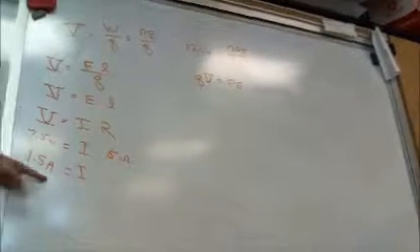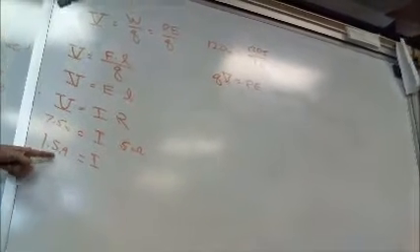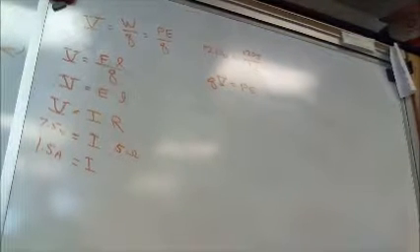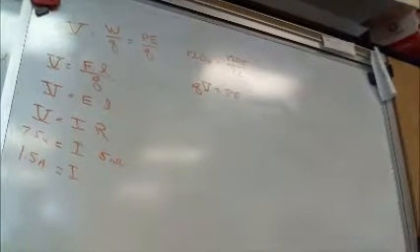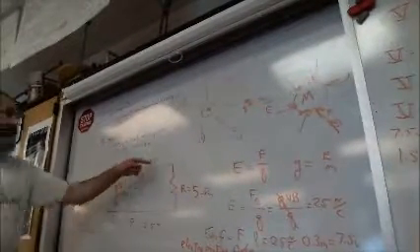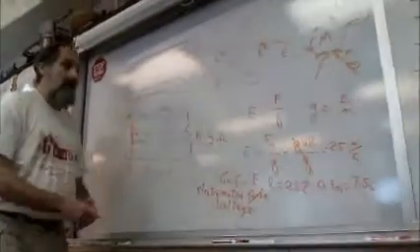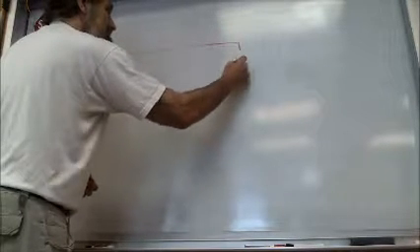1.5, who knows the units? Amps. Okay, for the viewers on this video, we're over here. V equals IR, 7.5 volts equals I times the 5 ohms, and 1.5 amps is the current. What is the direction of the current through the vertical wire? Through the vertical wire, the current would have to be up. And through the resistor, it's going to be down. We would say that the current is clockwise. So here we have those rails. Here is the resistor.